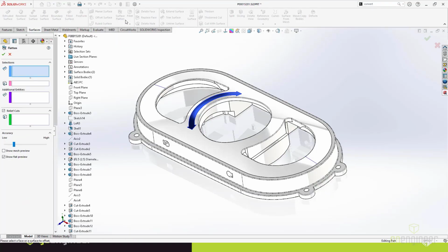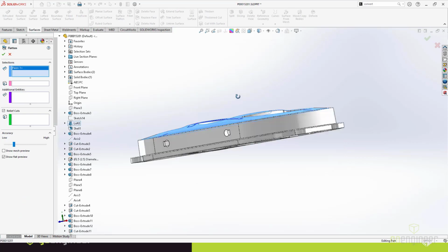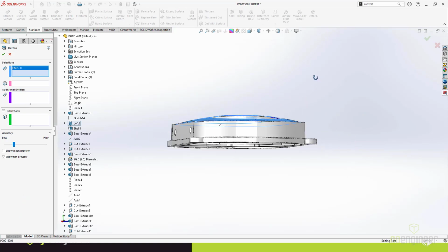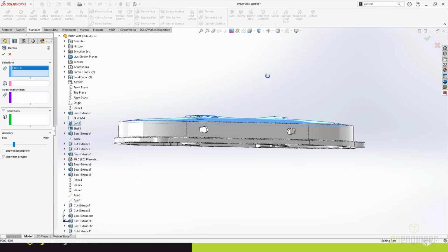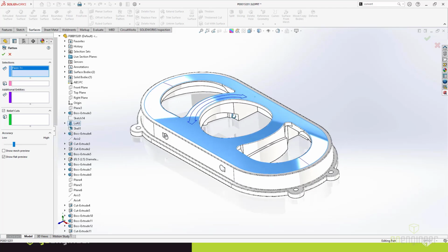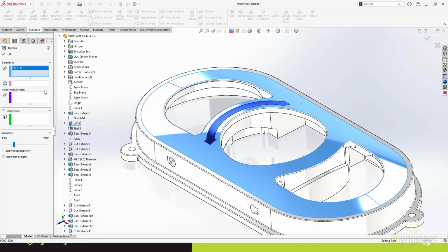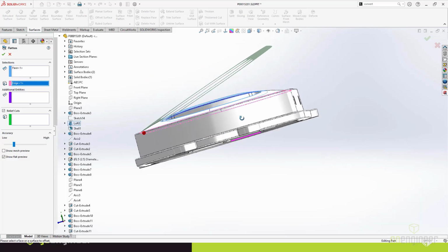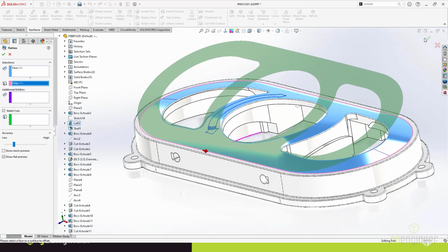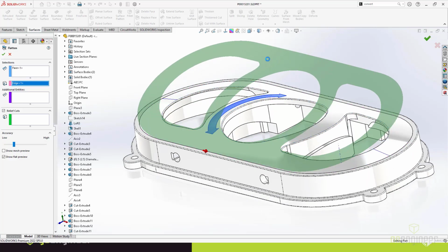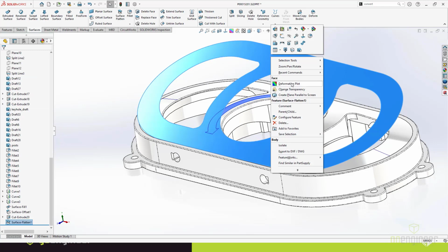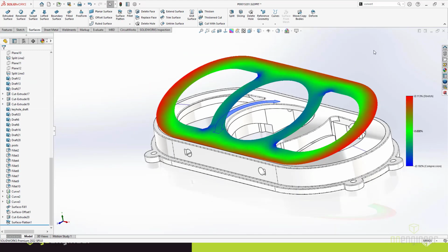But it enables you to select a face like this one here, which is actually domed in 2 different directions. So you can see that that is compound in both different ways. There's no flattening of that in a realistic sense. But by selecting the face and then any particular reference edge, we create a flat surface from that feature. What generally happens is you're going to get a surface that, if you right click on it, has a deformation plot that shows you the tension that you get from having a feature domed in 2 different directions flattened.